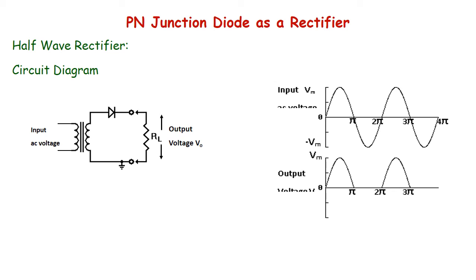That's your sinusoidal input voltage to the rectifier, which is available at the output of the transformer, and one end of the transformer is connected to a diode. Following the diode you have a load resistor which also acts as a limiting resistor, because once the diode turns on, current flowing through the diode can increase enormously.